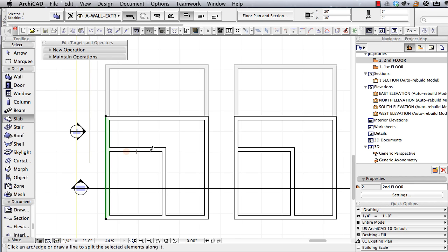I'll just go to where I have the reference line side and then say that I'd like to retain after the split this lower piece. But I found sometimes it doesn't like it, at least it won't complete the split this way. So I'll use the same split command, but I'll just click on this corner and then just draw a line in space, and then it definitely will split it.